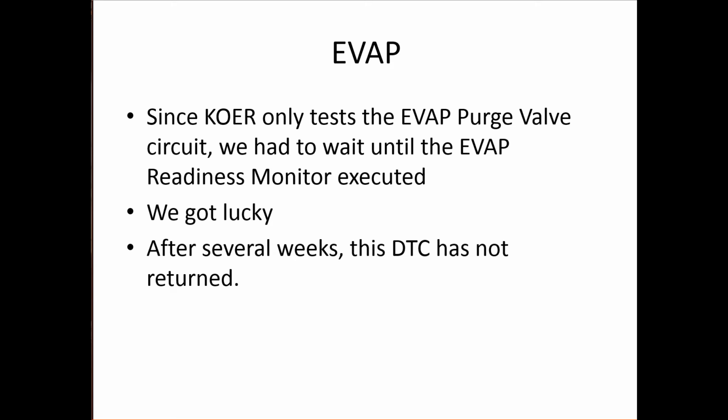Like I was saying, the key-on engine running test doesn't thoroughly test, doesn't execute all the OBD2 tests. So we knew we had to wait for the readiness monitors to execute. And in this case, we got lucky. We went with low-hanging fruit.